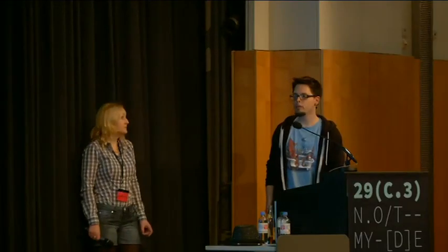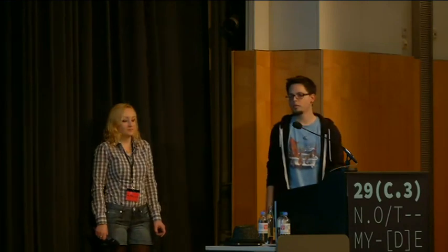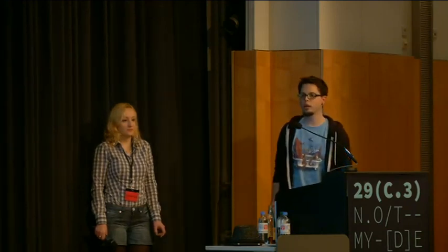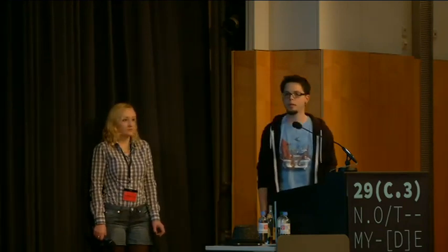Okay, next question on that microphone. Would this work with modern 3G phones? In theory, paging works exactly the same in 3G, so it should also be affected, but a 3G network is not the same as a GSM network. For example, if a phone is currently using a 3G cell, you don't see the paging for those. Even so, if you're not on a data connection, chances are high that your phone is using GSM because it saves battery. Thank you.